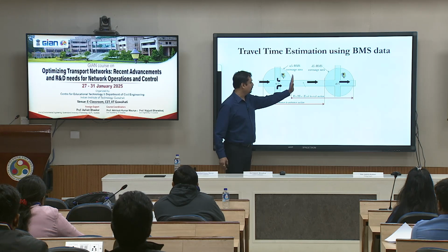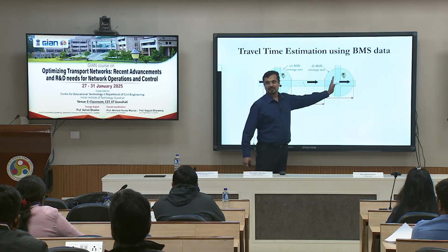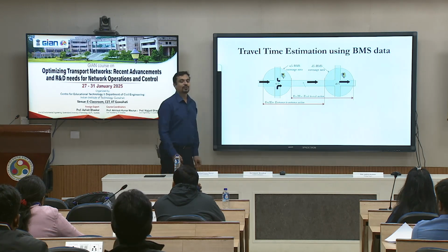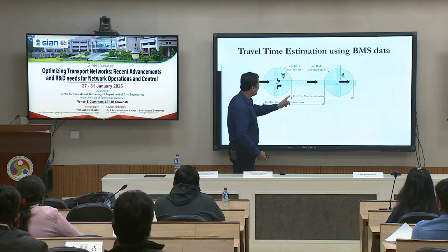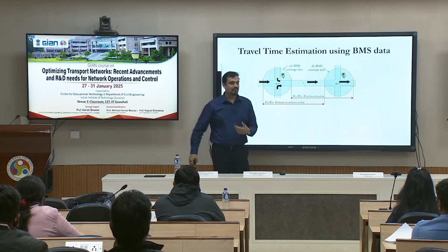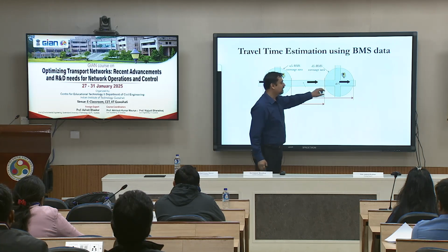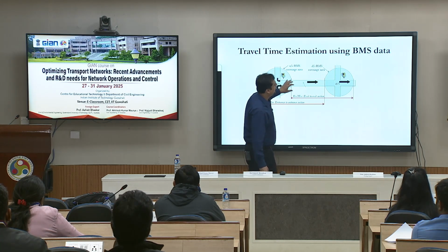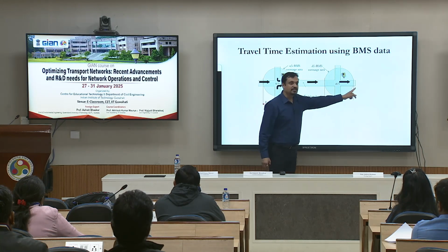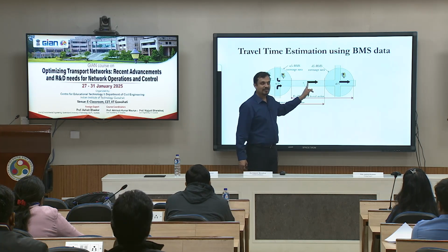Okay, so exit all. So you're looking from here, yes. Okay, so if you look at exit to exit travel time, it tells you how long it takes to travel from here to there, right? Let's say it takes you 3 minutes to travel, just for the sake of discussion. If there was no traffic signal, no delay, nothing, traffic might take maybe 1 minute to travel. But you observe 3 minutes, then that additional 2 minutes is the delay on this road, right?